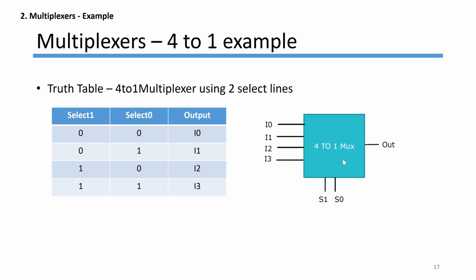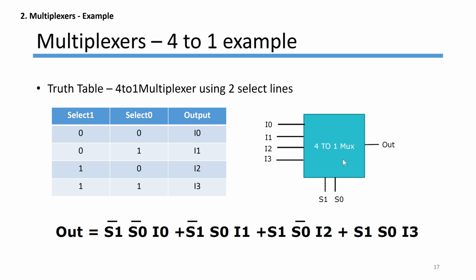So you draw out your schematics, you check your schematic, and then you create your symbols, and the symbols should come out along the lines like this. From this truth table, you should also derive the Boolean expression, and this Boolean expression is what forms your schematics.